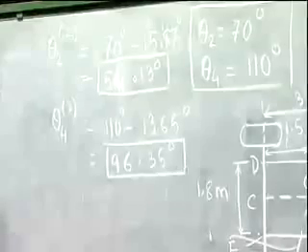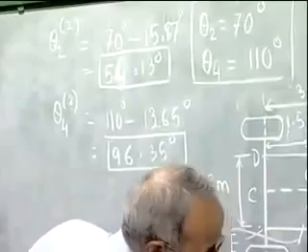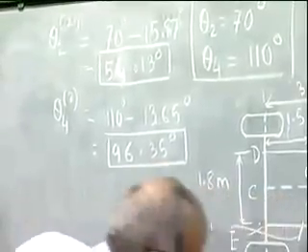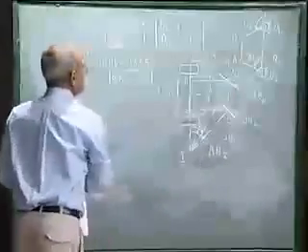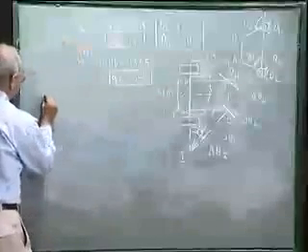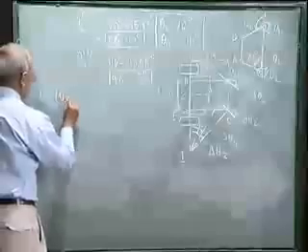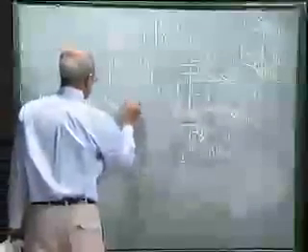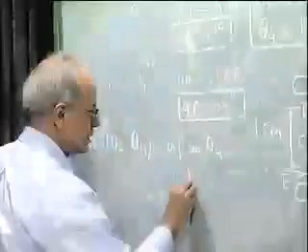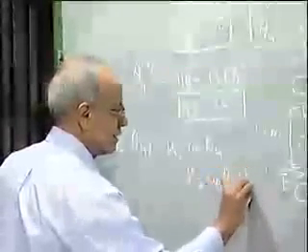So we get two pairs of coordinated movements, the two pairs of values of theta 2 and theta 4, which must be satisfied by this 4-bar linkage O2, A, B, O4. So we write the coordinate equation, cosine theta 2 minus theta 4 is K1 cosine theta 4 minus K2 cosine theta 2 plus K3.